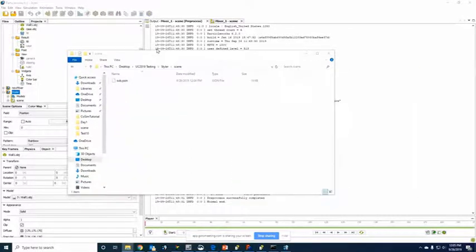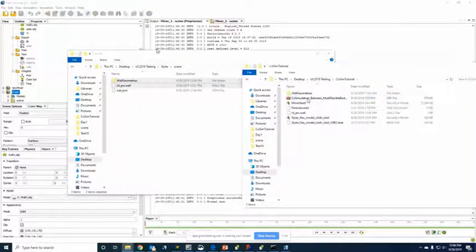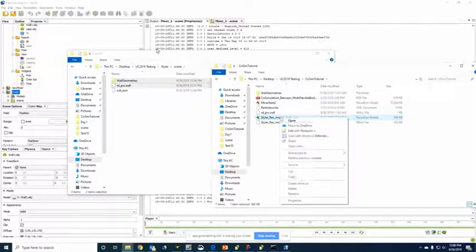So I'll go ahead and get to my location where I saved those folders. And so I need this RecurDyn Particleworks .wall file and the wall geometries. Copy and paste. And then I also need this styler flex model cloth file that I was working with. And so I copy and paste that as well, all into the scene folder that's in Particleworks.